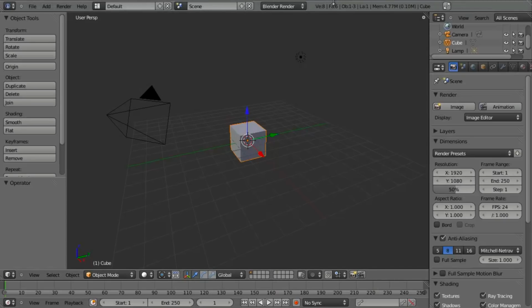So over here in Blender, the first thing that I want to do is set up just basically a reference object for the size of our entire container. And the size of this is actually going to be pretty standard. These come in several different sizes, but the size that we're going to use, based on what I can see from the picture and having looked up the actual dimensions of these, is, in the American system, 19 feet 10 inches long, 8 feet wide, and 8 feet 6 inches tall.